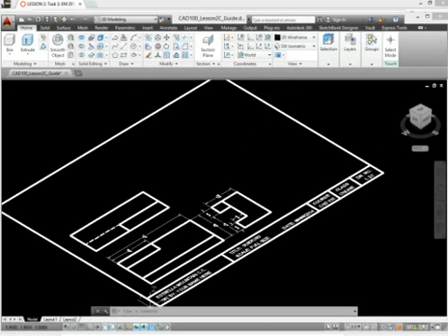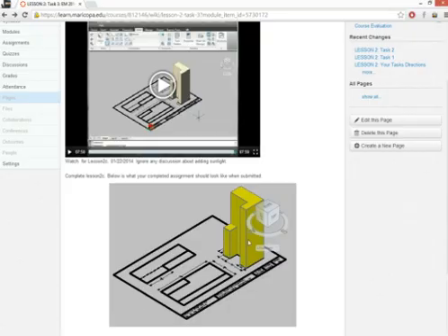We're going to be using the right side view in this case because we have two extrusions that, when they are pulled out, will make the shape of the feature you saw in the assignment right here. You can see this extrusion here will pull up. You'll see this extrusion will go up and then they'll be unioned together.